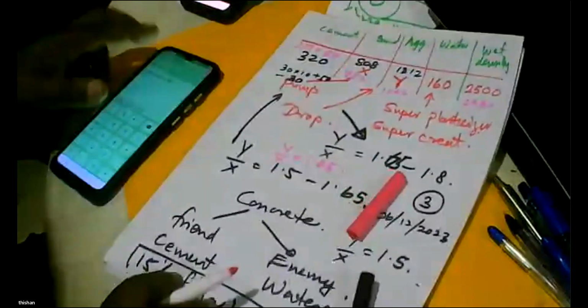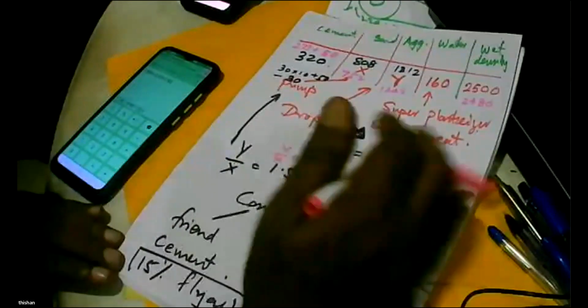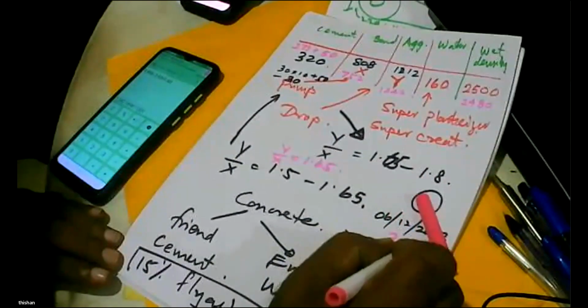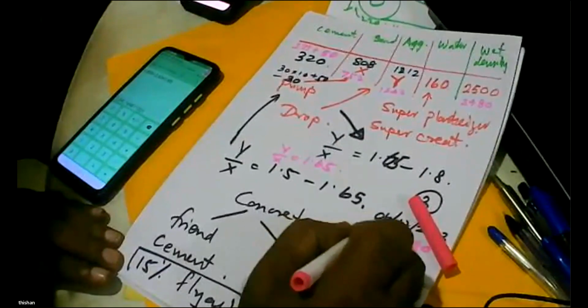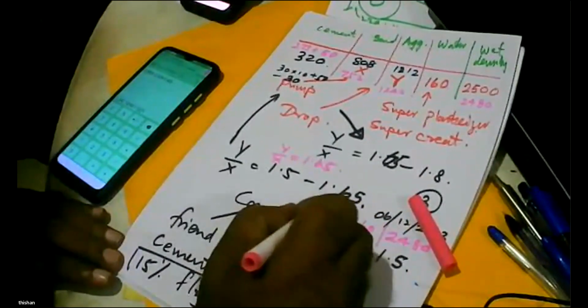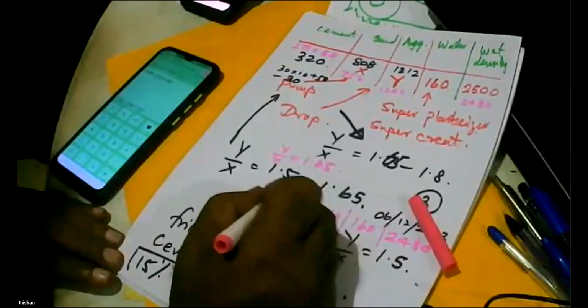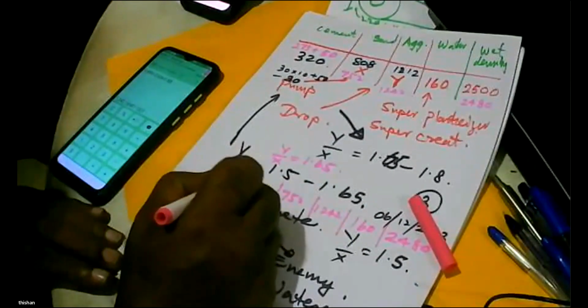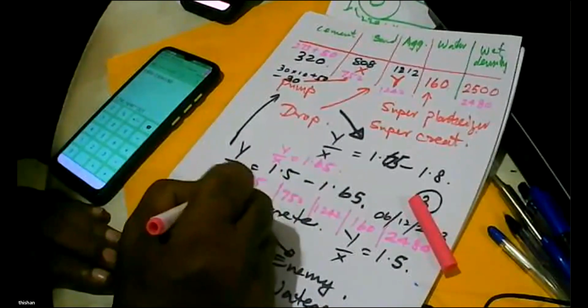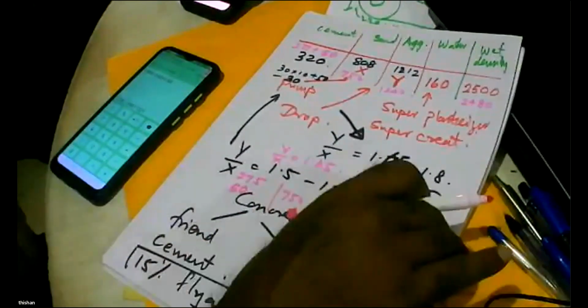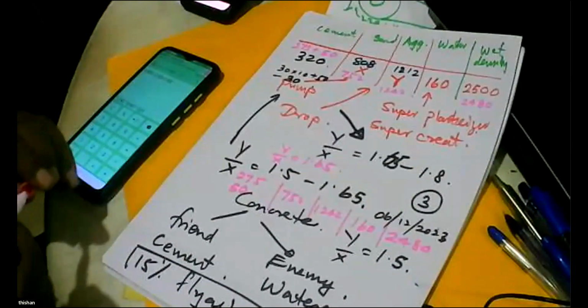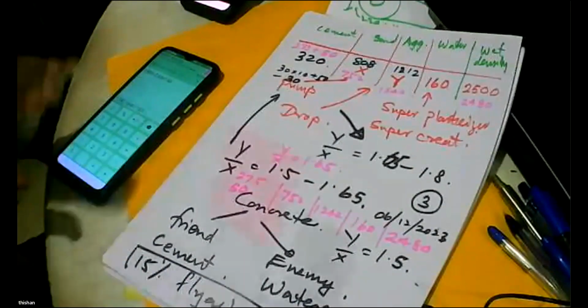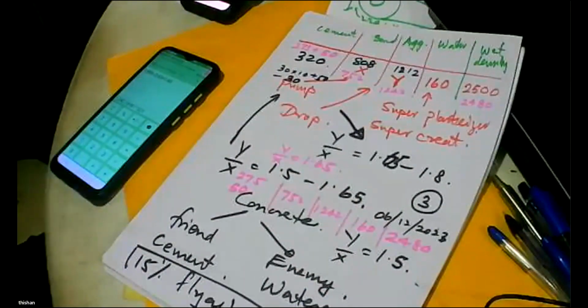So you can see the numbers are 2480, 160 water, 1242, a little more aggregates, less sand. What is the main difference? 275 cement, 50 fly ash. What is the maximum temperature that this will reach? The maximum temperature of this mix will be 70 or below 70.